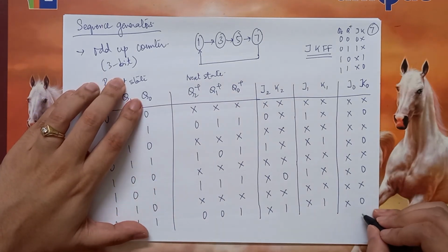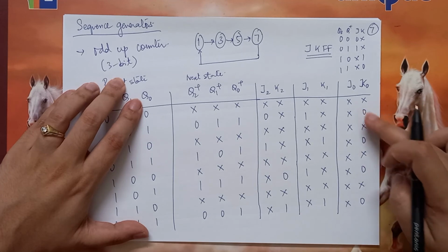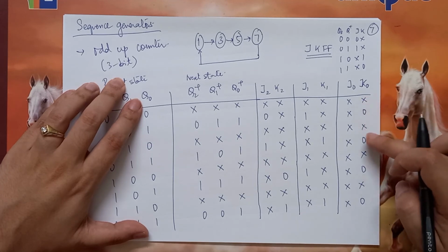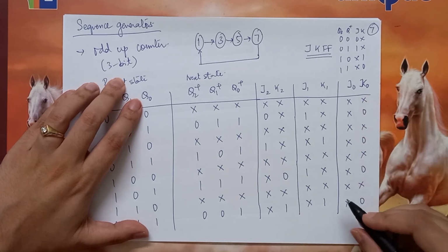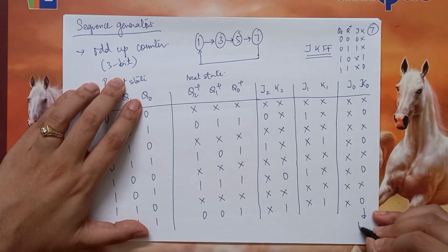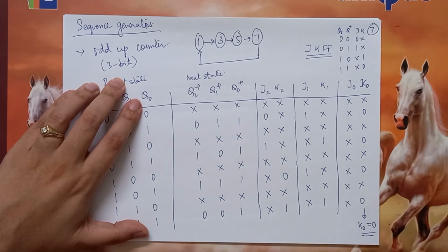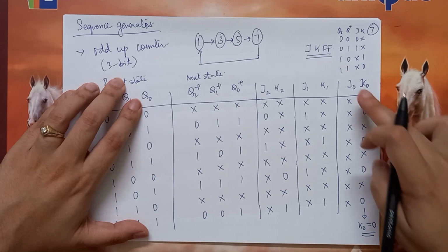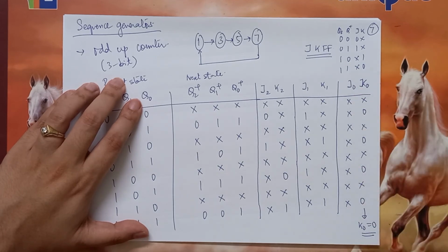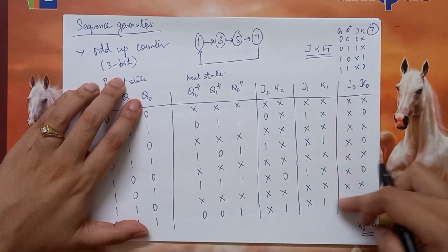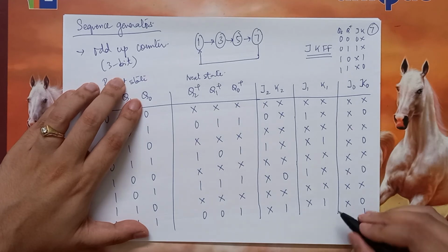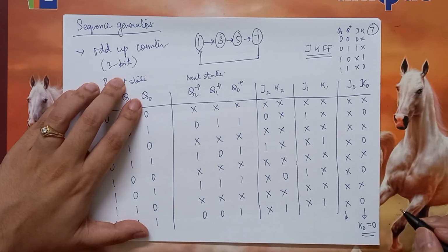So over here, some things you can make out manually. For K0, we just see zeros. Others are don't care. So you can very easily say K0 is 0. That's it. You can consider this don't care as 0 and make a group of 8. Now J0 is very interesting. You can make J0 as either 0 or 1. It seems it does not matter.